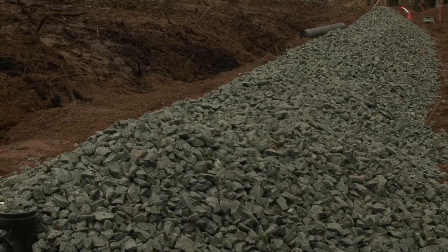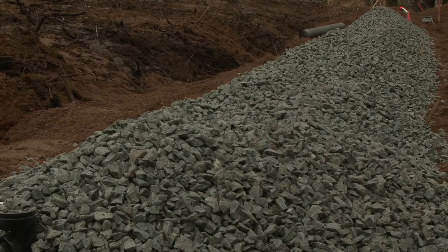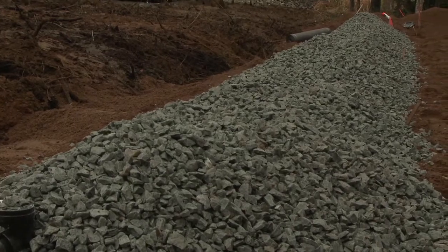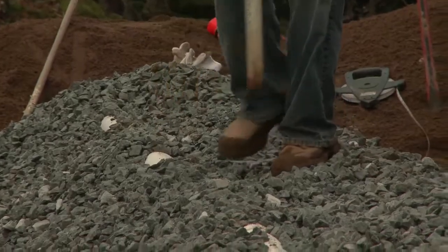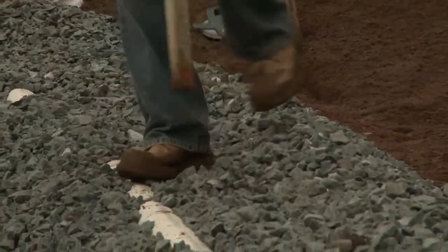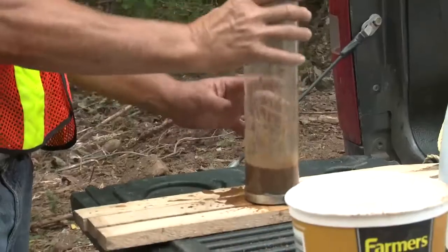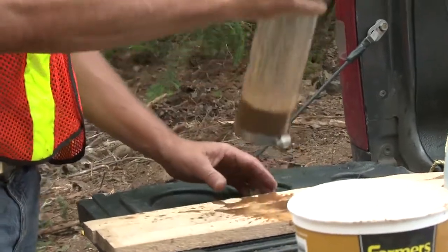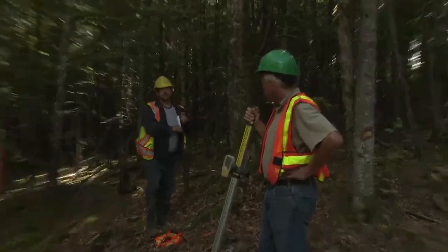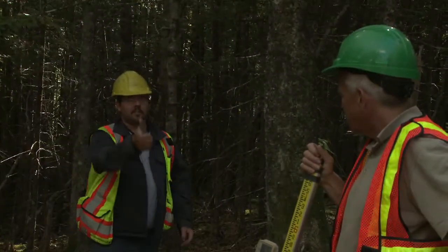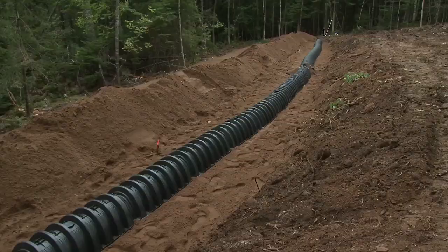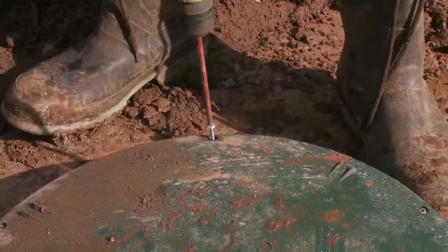For a gravel and pipe distribution trench, the length and slope of the pipe would be verified, as well as the depth of the crushed rock above and below the pipe. The QP checks the permeability of the sand. The QP advises the installer that the system has been installed correctly, and when the 3-day notice has passed, the system may be covered. The lids on the septic tank are fastened down.